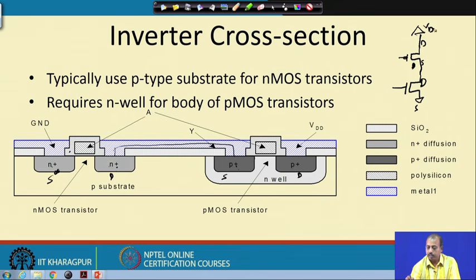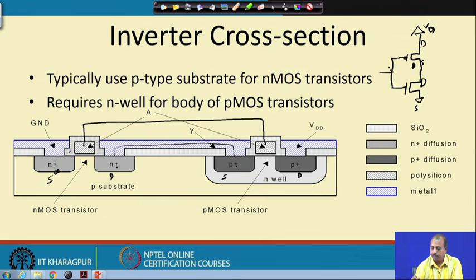So, this is connected to VDD as it is shown here, and we have these two gate terminals available. These two are to be shorted, and the A input has to be connected here, and I have to take output from this point. This is the shorting of the two.